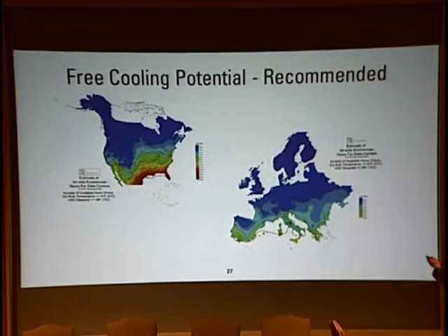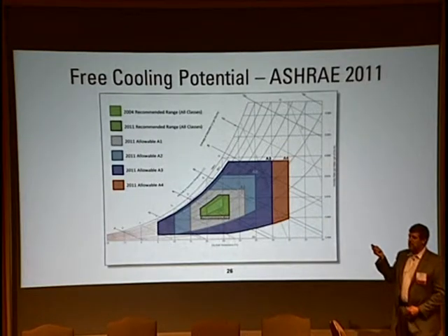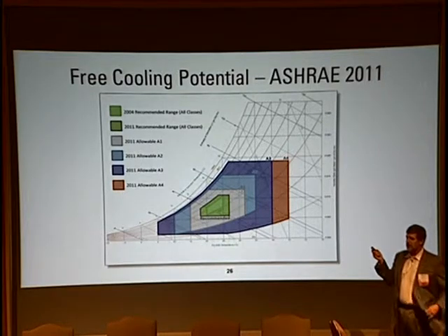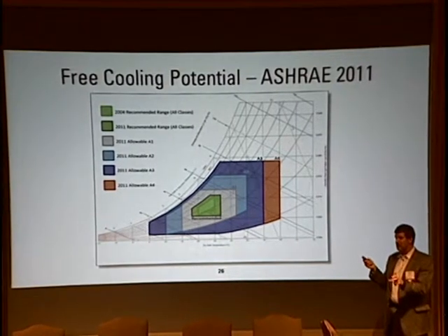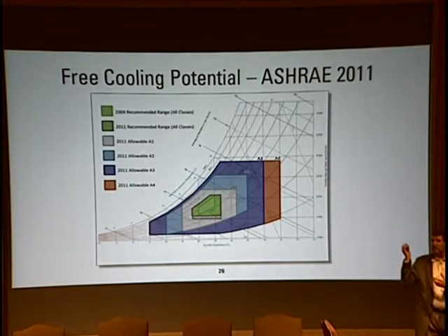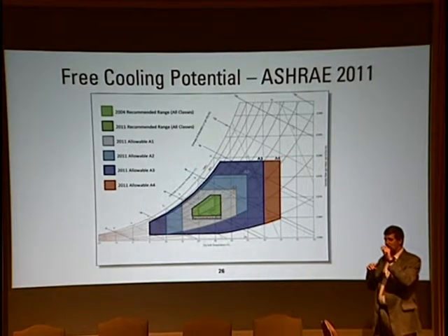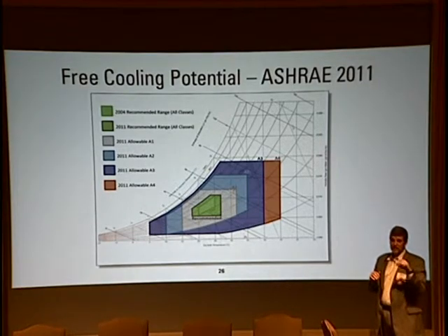When ASHRAE published the widened specifications, one of the biggest parts of this paper was a commentary about the reliability, and they do calculations that are sanctioned by the IT equipment vendors that say these are the ranges that you can expect if you increase or decrease the operating temperature. And they show for a number of cities, when you use 100% free cooling, you'll spend some time above and some time below, and the net effect, in like 11 of the 15 cities that they profile in the paper, most of the major sites that Jeff's talking about, is that the impact is either none or you actually get an improvement in the reliability.